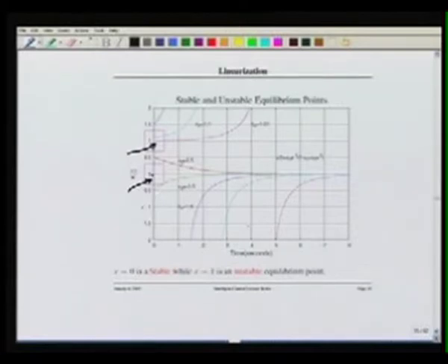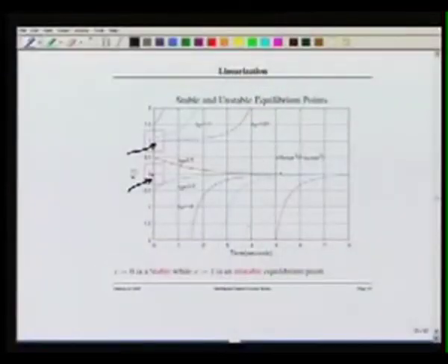So, if I give the initial condition as minus 0.5, you see they all settle, and for plus 0.5, wherever I start in this zone, they are all going towards 0. Finally, the system at t tends to infinity goes back to the equilibrium point 0. That is, if the system is disturbed slightly from its equilibrium point 0, near the origin, it goes back to the origin.